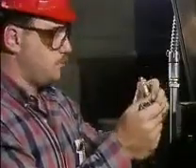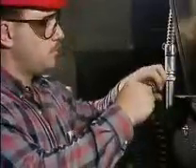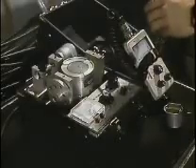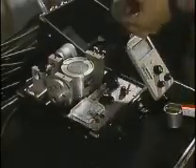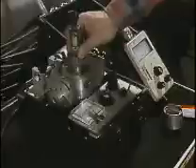Also, before the meter is used, the transducer, the cable, and the meter should be visually inspected for signs of damage. In addition, if a vibration meter is due for calibration, it should be calibrated before it is used.